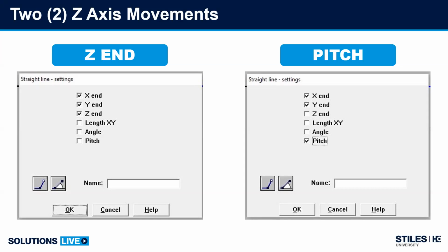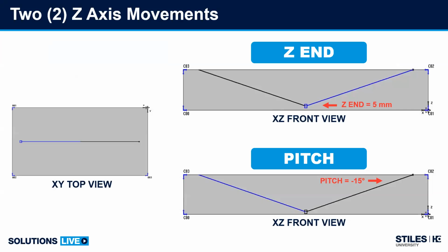You're telling a line to move in a specific dimension in X, Y, and depending on how long that line is, your angle could project the tool well below the panel. So again, I'll show you some examples. Just have to be aware, we don't use pitch very often, but if you know that you have an angular move, you already have that number, so we can use that.